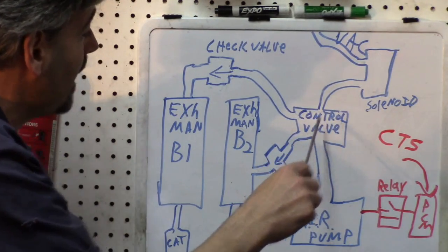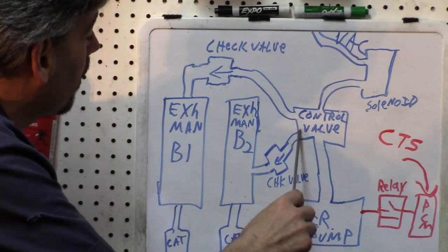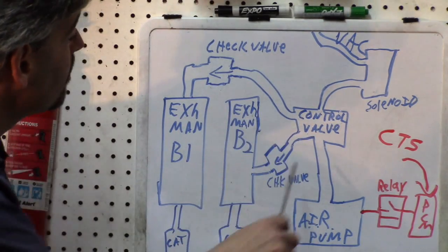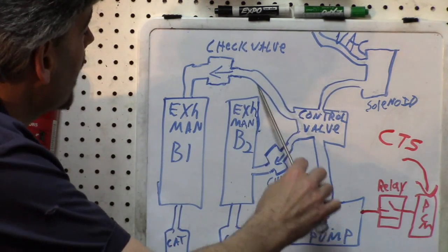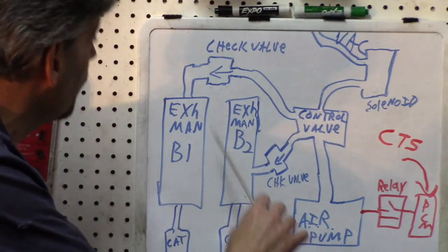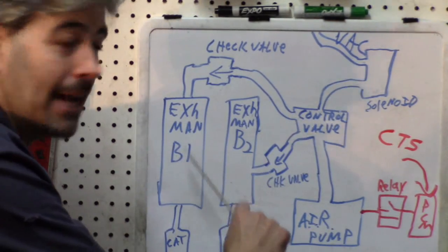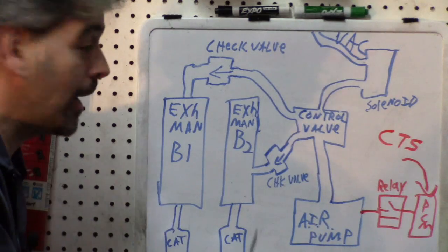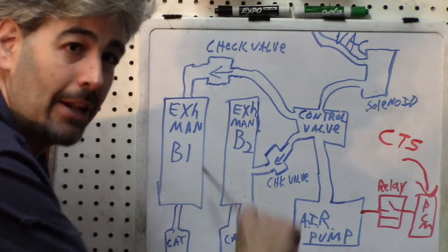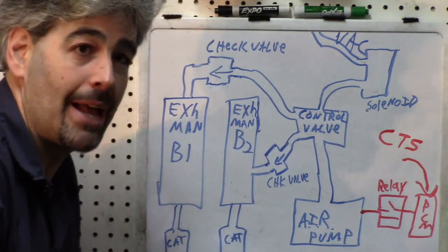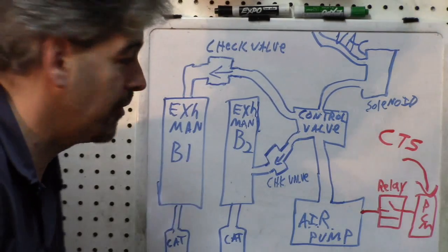And when the vacuum is applied to the control valve, I think some systems also call it a diverter valve, that will allow the air to come directly through these tubes past check valves. The check valves are to ensure that the air direction can only be towards the exhaust manifold, so air can only go in one direction. This way, exhaust from the manifold cannot back up into your air system, possibly causing damage. And then the air enters the exhaust manifold directly and causes the activities that I mentioned earlier. And these, of course, here would be your cats. And of course, in my car, Schrodinger's cats.